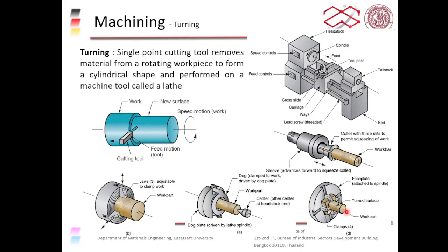You get a cylindrical shape, but the cross section is more elliptical, not circular, right? Because you are cutting one face more than the other face, it becomes flatter on that side, and the other face is cut less, so it's more rounded. So you get an oval or elliptical shaped workpiece.